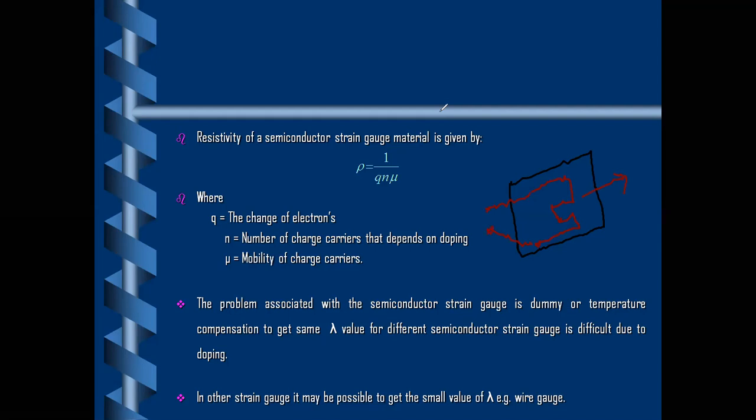So we are saying that this much is the force. Force is directly proportional to the output generated over here. The output is the variation in the resistance generated when it is connected across the Wheatstone bridge. So the output is in terms of voltage. Suppose I have considered E0.